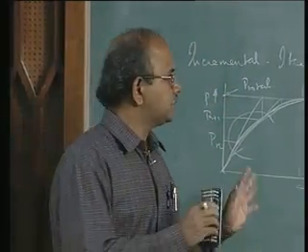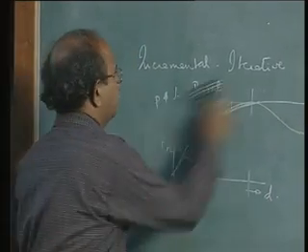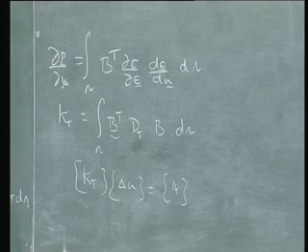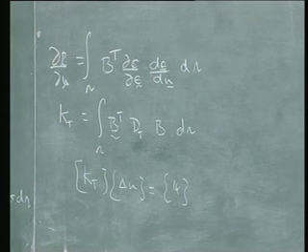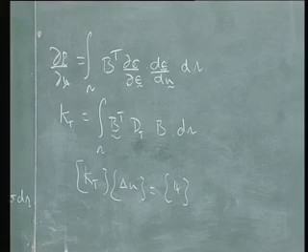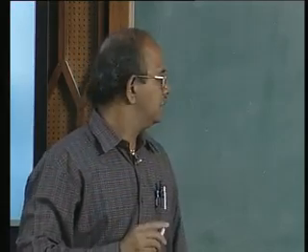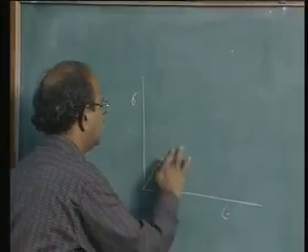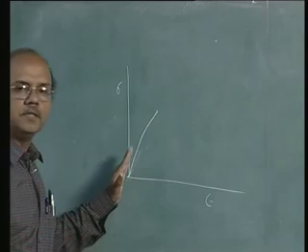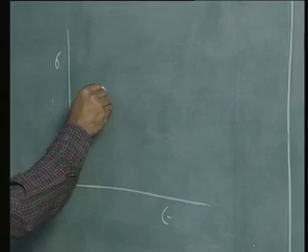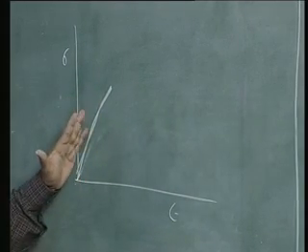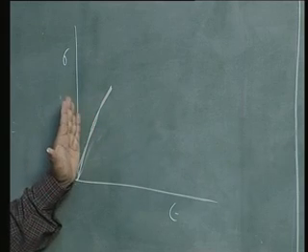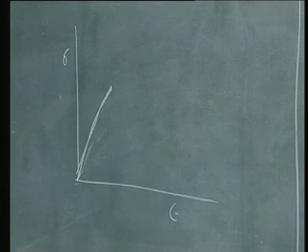Okay. Now let's look at these things for an elastoplastic system. I'm sure all of you know the stress strain curve quite thoroughly. A few points which I'm sure all of you remember: the elastic part of the stress strain curve, I mean, it's an exaggeration, actually it won't be so far away from the axis. Usually E will be so very large that it will be very, very close to the axis. Now just for clarity I am drawing it like that.